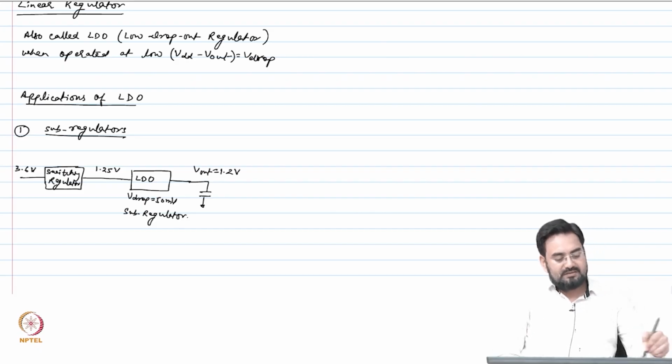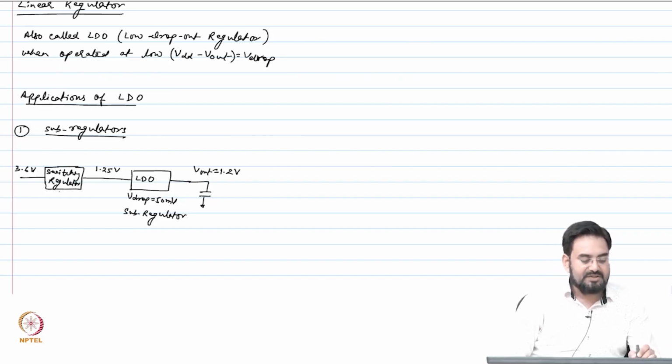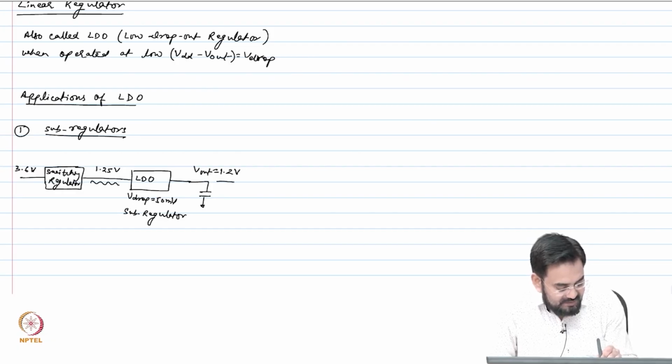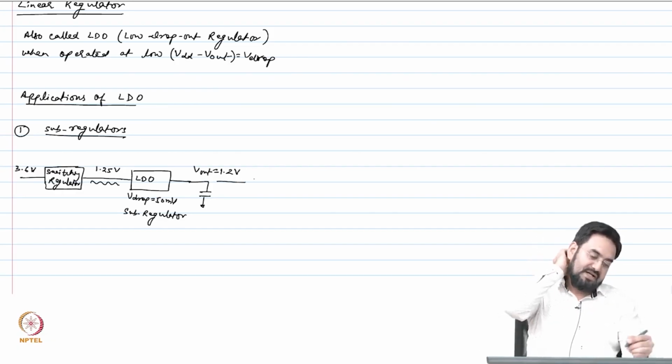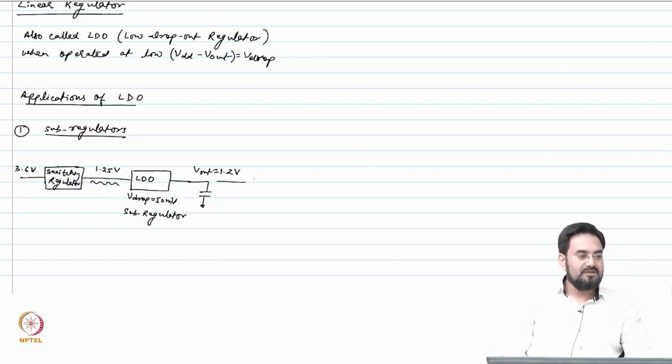So most of the portion step down, basically the larger step down ratio is achieved by switching regulator, and mainly due to efficiency reason, we know. And since this guy has ripple, and this will be much cleaner. This is what LDO will do, it will filter out your ripple and provide you a cleaner output. Okay, and it's very commonly used in any system, especially noise sensitive application, to achieve higher efficiency as well as smaller output ripple.